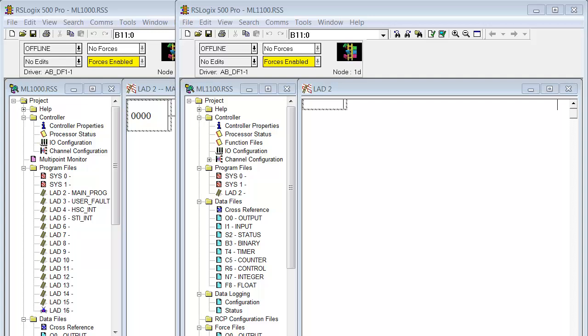Then there's the I/O module status file. Now none of this is available for the 1000. This is all the 1100 or the higher processor numbers, like the 1200, 1400, 1500, etc. The function files always exist in the processor in non-user memory. They are a fixed length and reside at a fixed address in the processor.